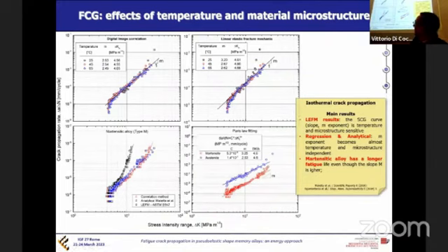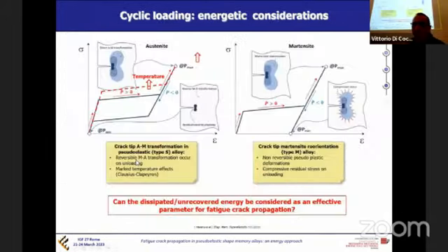We built the crack propagation curves as a function of the effective stress intensity factor captured by our special methods. And we have observed that there is a marked effect of the temperature in pseudoelastic, but also a marked effect of the microstructure. That's why now we are looking at a different parameter. So we are trying to understand if these effects are related to the material hysteresis.